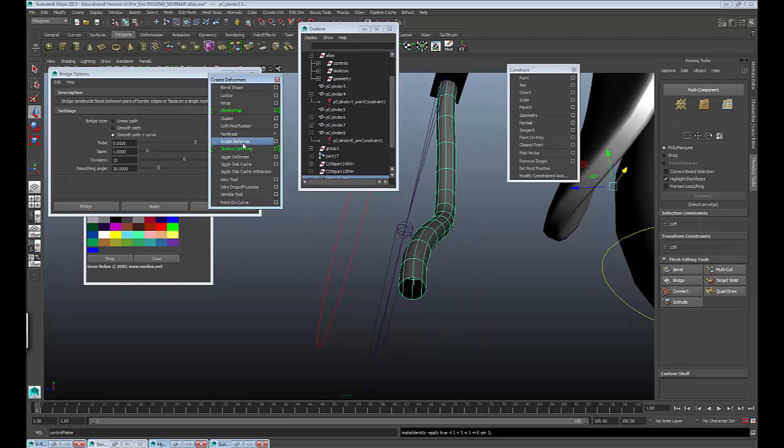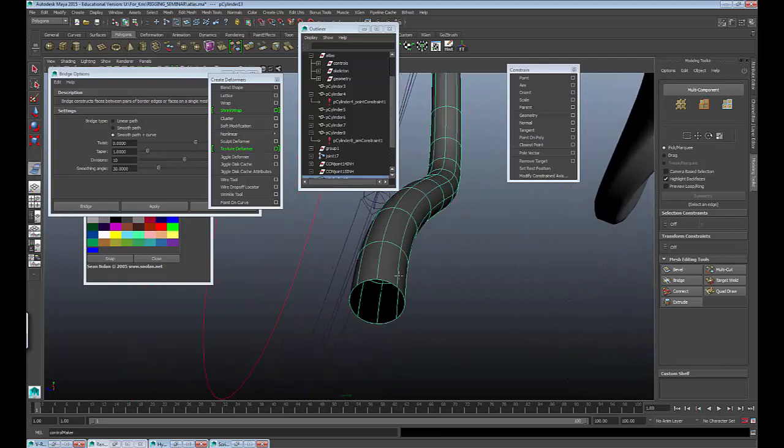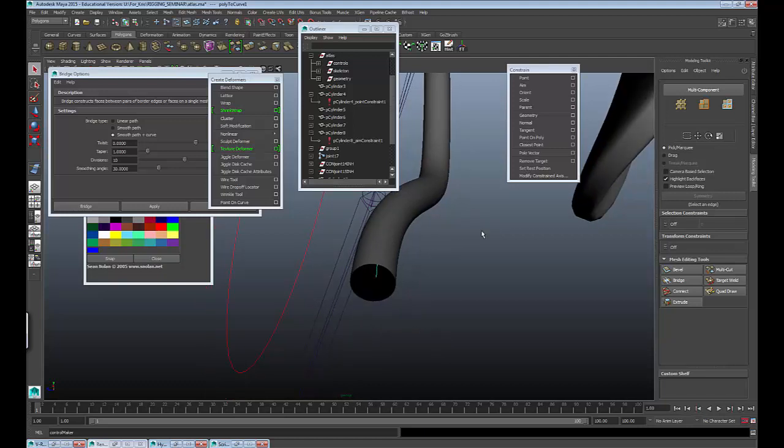And we're going to go to what's called the wire tool, which is right here. So what you have to do is select the wire first, then hit enter, and then you select the... let me do this again. Wire tool, so select the geometry, hit enter, and then click on the wire, hit enter. There we go. Geometry first, hit enter, wire, the curve, hit enter. You have to hit enter twice.